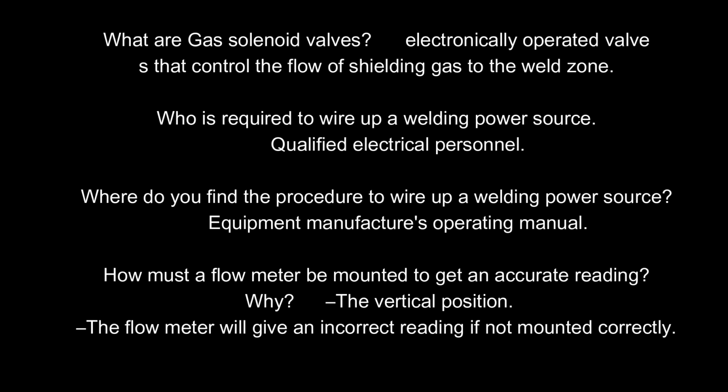Who is required to wire up a welding power source? Qualified electrical personnel. Where do you find the procedure to wire up a welding power source? Equipment manufacturer's operating manual. How must a flow meter be mounted to get an accurate reading? Why? The vertical position. The flow meter will give an incorrect reading if not mounted correctly.